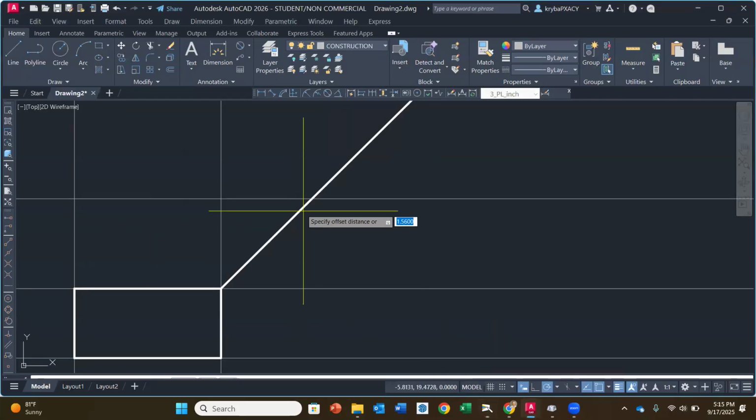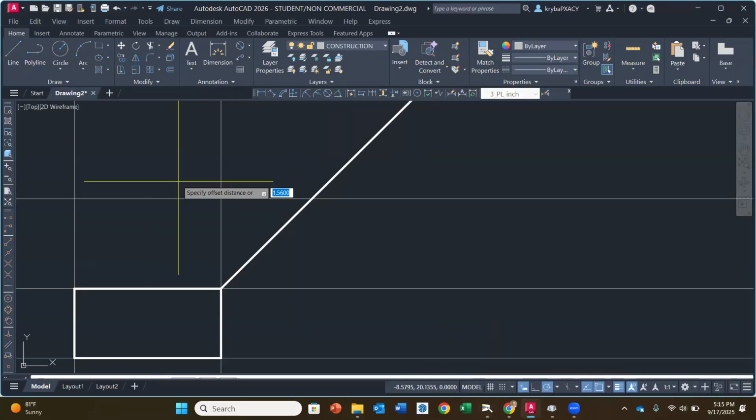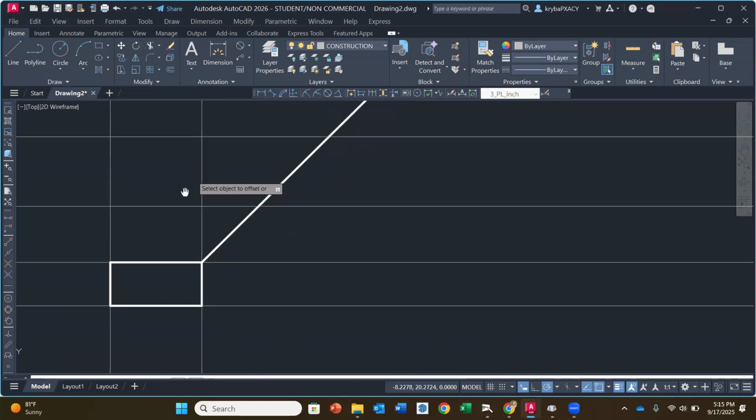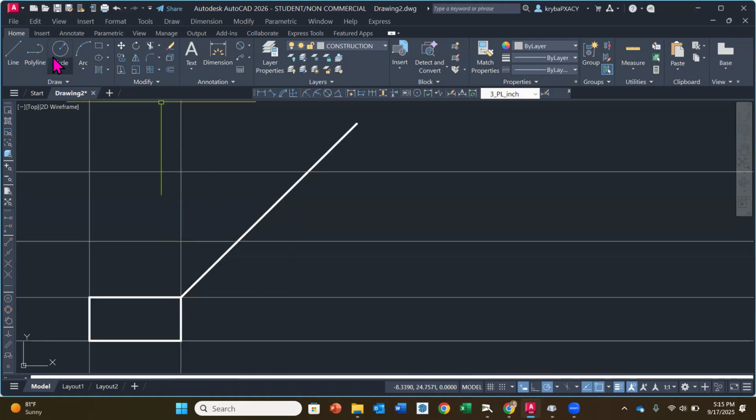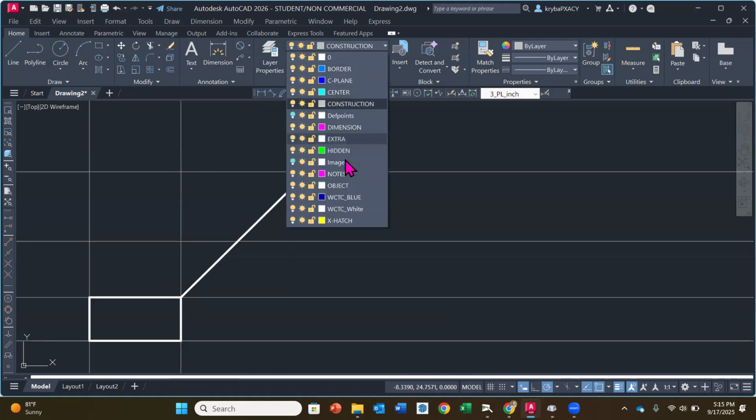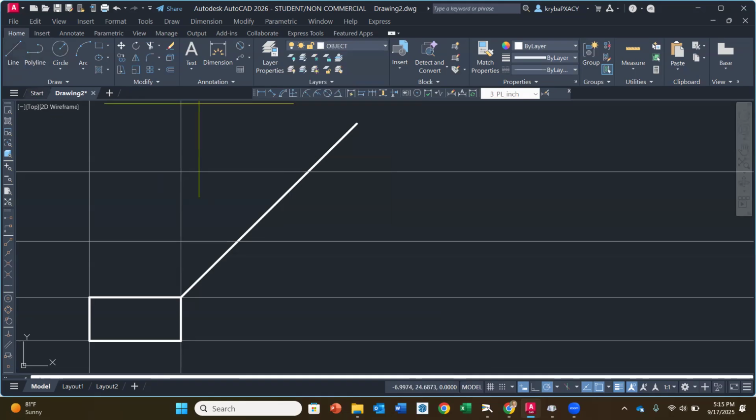So I'll go back to AutoCAD. We're going to offset 2.5. I already put the offset feature in, and it should be there. There we go. There's 2.5. And now I'm going to go back to my object line layer and just create the rectangle for the perimeter around the outside with those four points. Okay. So that's my top view.